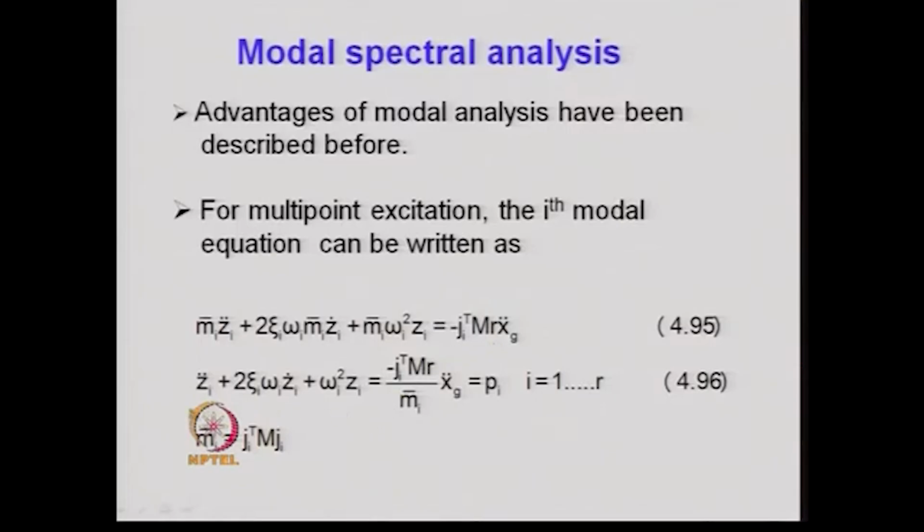Then one can convert this to this form by dividing by m bar i, and this entire thing is called P i, that is the generalized force for the ith mode. So, in other words, this is the ith modal equation, and in that m bar i is defined in this particular way, that is already known to you.